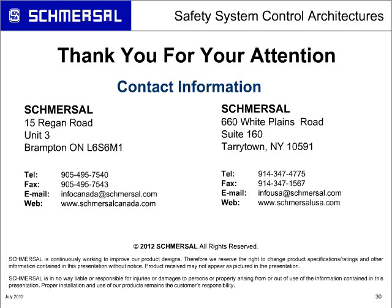Where a maintain emergency stop device actually maintains that those normally closed contacts stay open until you mechanically reset that. When you read any of the standards, whether it's NFPA 79 or ISO 13850 or EN 60204, you have to have a maintain push button, and it has to be that push-pull, twist-release, needs a manual reset before you can start re-engaging or re-enabling the rest of the circuit. So that definitely is a required. No momentary push button is an emergency stop by any standard today. So it's definitely a potential issue as an emergency stop device.